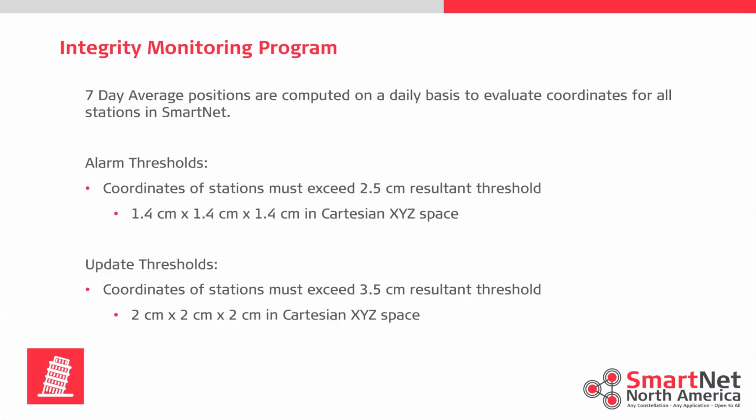From an integrity monitoring perspective, this is how we wrap everything together. It's also how we position new stations as they're brought on and then evaluate stations on a daily basis. We compute a 7-day average of positions in the reference frame that we're operating in. We have alarming thresholds and update thresholds set. So coordinates of stations must exceed 2.5 centimeters.